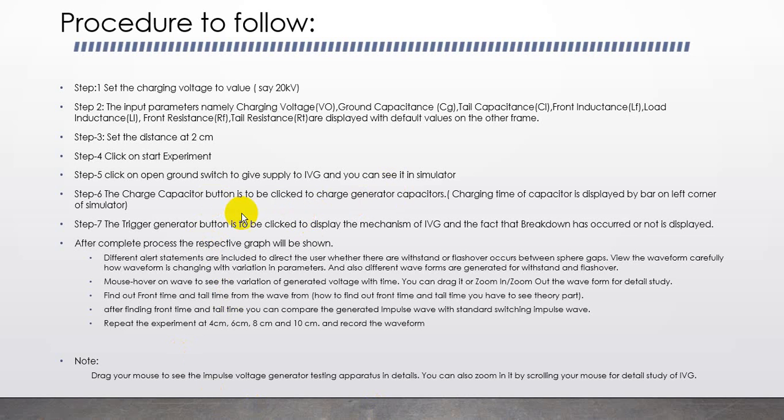After clicking on this charging capacitor, a pop-up window will appear where you can observe an impulse waveform. If you study this waveform, you will find the peak voltage, the tail time and the front time. We will observe this.